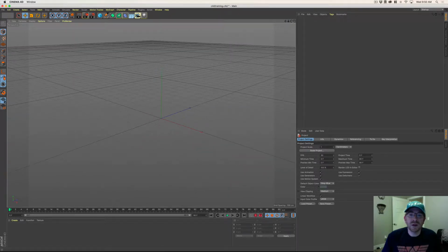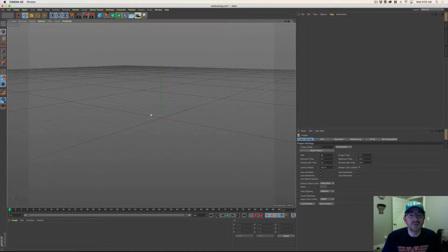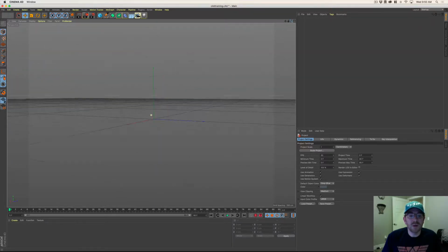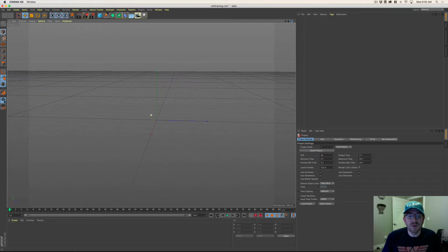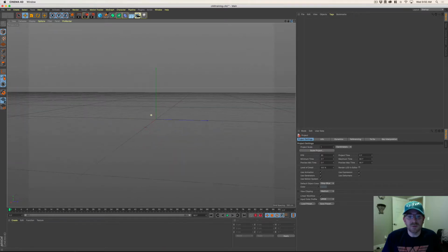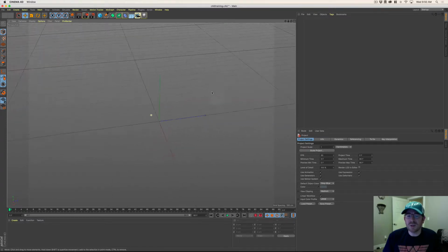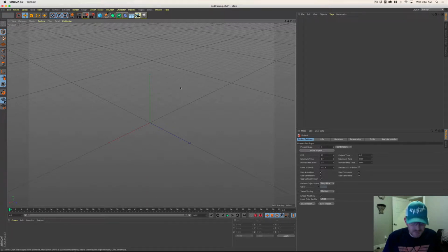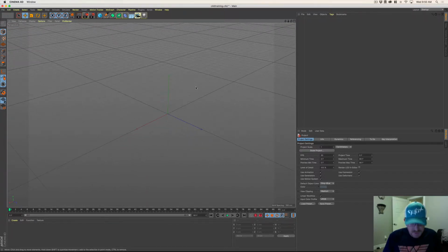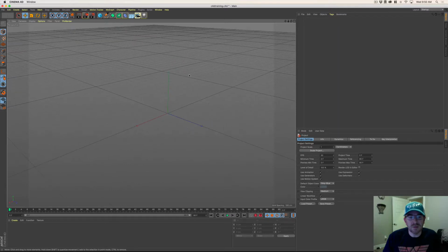Then there's rotate or orbit. So you can rotate or orbit with this button, clicking and dragging kind of in a circle. Or I prefer holding the Option or Alt key and then clicking and dragging, a little more control, but I prefer that. So navigating is pretty easy, but this will take you a little bit of time to remember. Oh, yeah, that's orbit, that's pan, so practice.